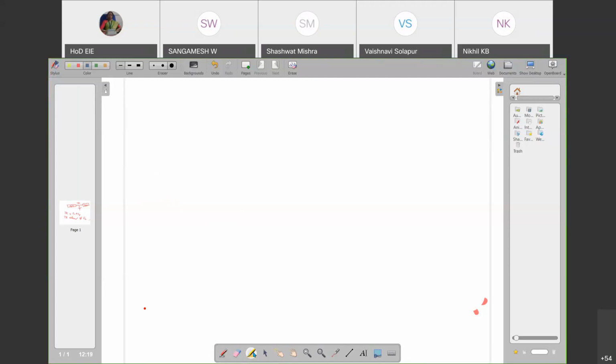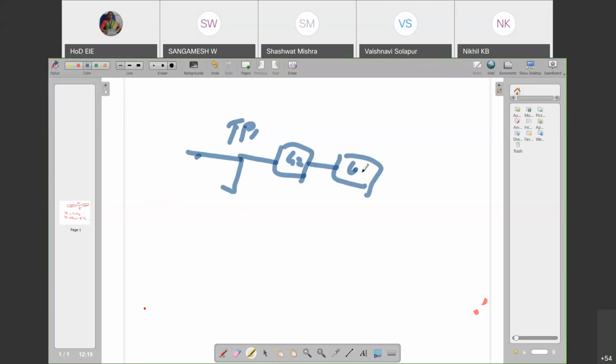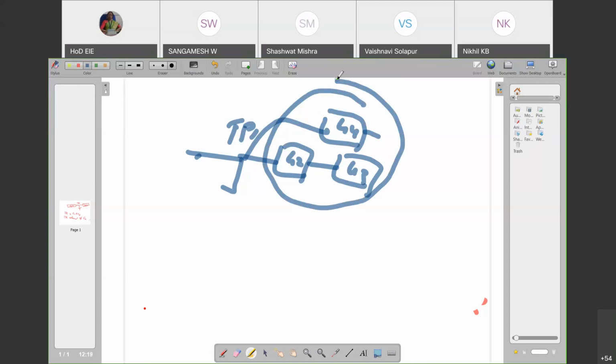Then when you look at the changed block diagram, you would be having a takeoff point TP1 here, and your G2 is here, your G3 is here, and it is in parallel with your G4. So now you replace these things. Step 2 is to replace the 3 blocks as G2, G3 plus G4.